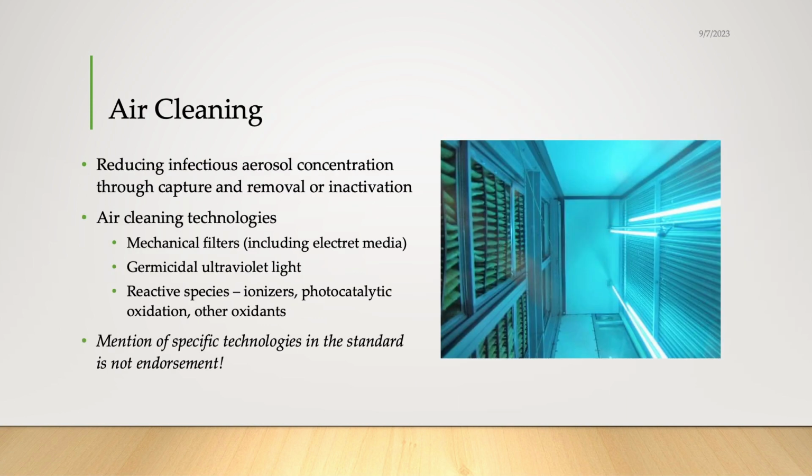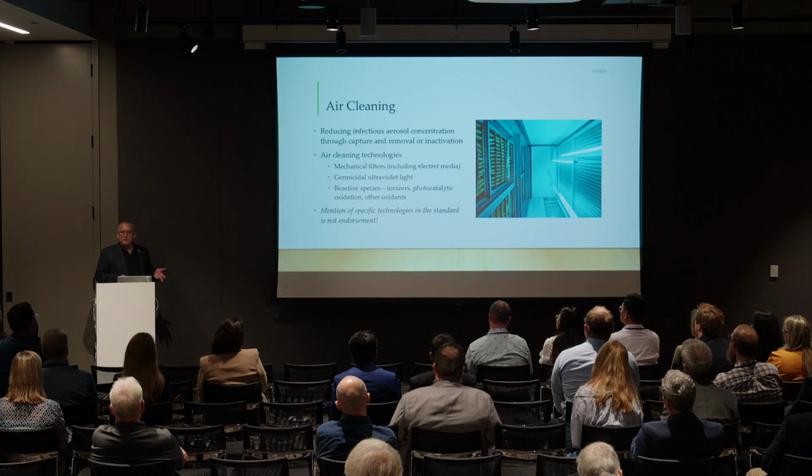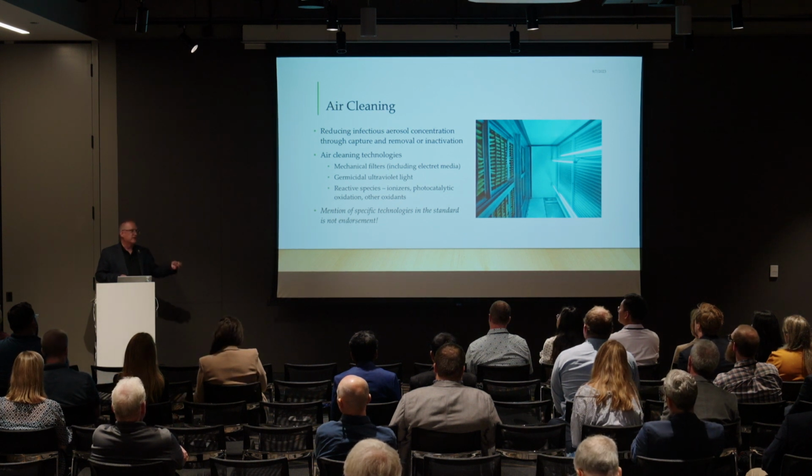Air cleaning is really important in this standard because efficient compliance with the requirements is important. We understand, because there was pushback right from the beginning of the pandemic, that lots more outdoor air was a problem because it was going to cause more energy use. So we emphasize not promoting but enabling the use of alternatives to outdoor air as a way of controlling concentration.